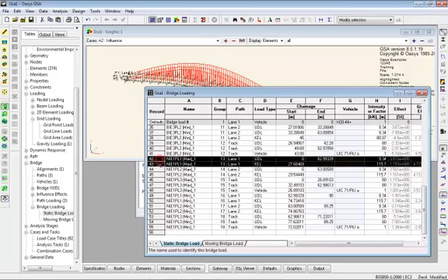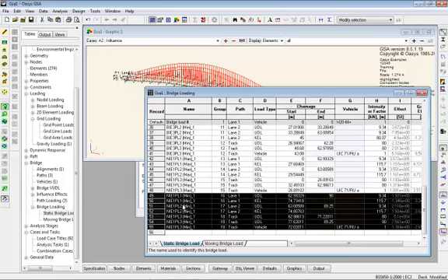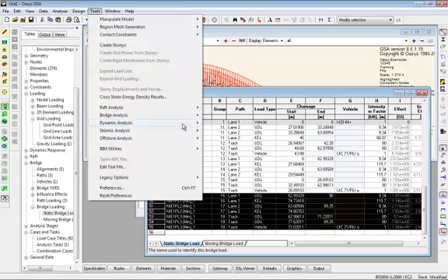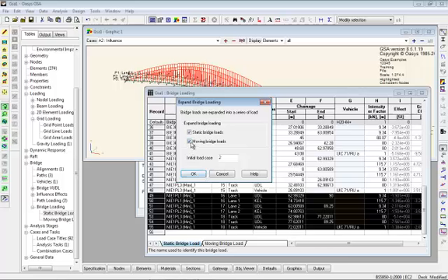For example, if we take these ones here, these are nodal influence effects for our first effect, and these will be producing maximum reactions at that point. These ones will be producing minimum reactions at that point, and likewise the beam effect, and so on. If we could delete ones out of here, we can judge will not be important, but I'll leave them for a moment, and I'll just expand these bridge loadings. And we don't need the moving bridge loads because that's my vehicle from earlier.